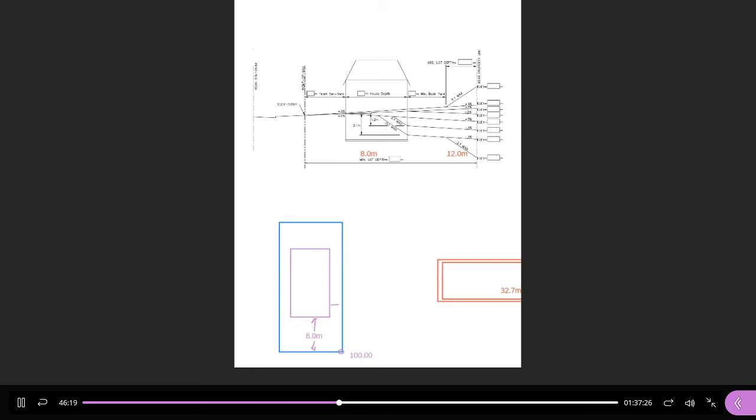The typical setback in the side yard is 0.6 or 1.2 meters, either 2 or 4 feet. It's relatively short compared to 8 meters, so keep that in mind. We're going to do a very crude calculation. If I want to know the elevation of the corner of the building here, I need to come up from the front and calculate the elevation opposite that point on the lot line.